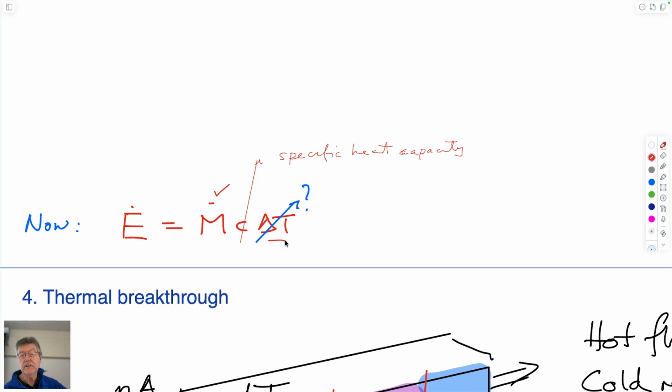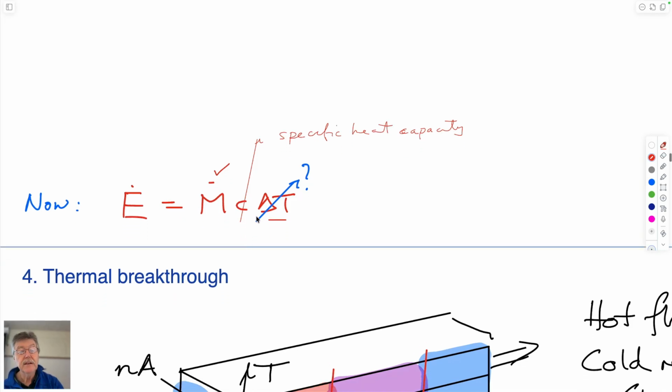However, if we don't guarantee that the fluid is coming out hot, then we don't have any thermal energy. And so that's the second one. We have to have both of these. Can't just have one. We have to have both. And so long as our water is our heat transfer fluid, this is always a known quantity, and we have no ability to be able to change that. We could change mass flow rate by stimulating our reservoir or hydraulically fracturing it to increase permeability.